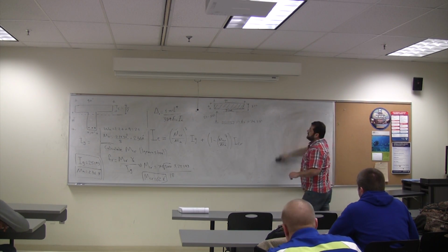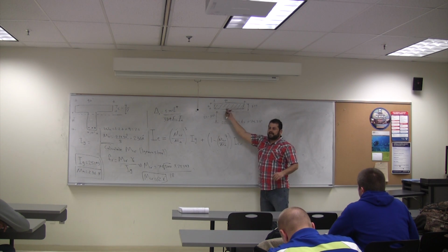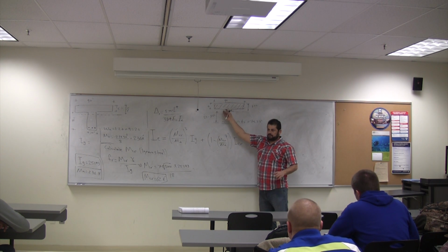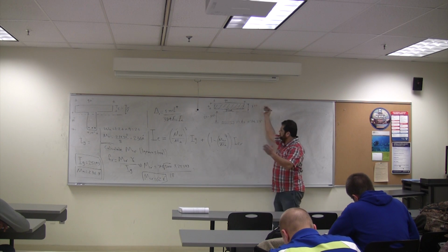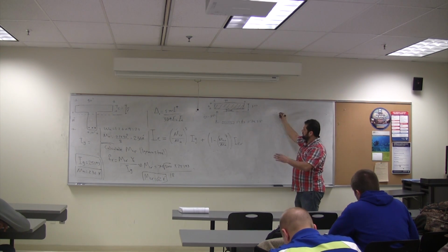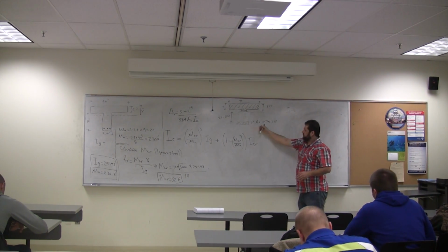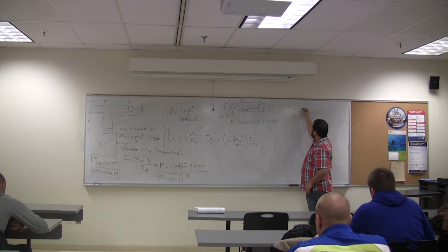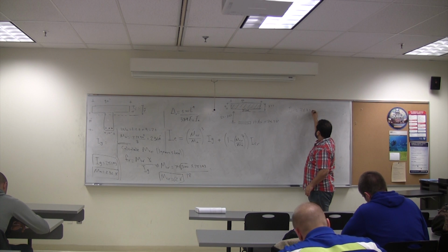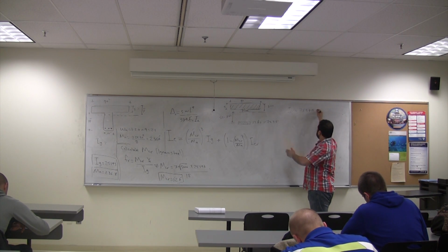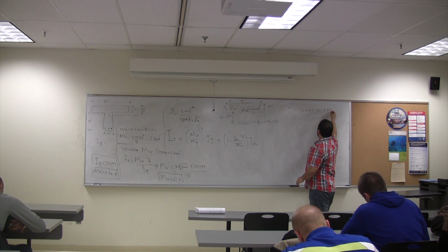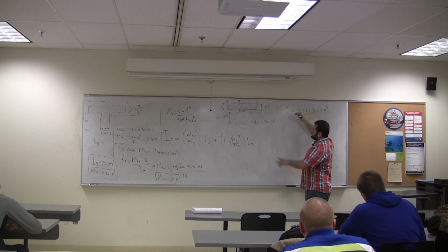Okay, I'm not going to take this small piece, although I can. It's easy to do. We'll take everything. So I crack equals the following. I'm going to start with the steel. It's NAS, which is 7 times 3.81 times the distance from there to there, which is 22 minus 8.62, squared. Done with the steel.